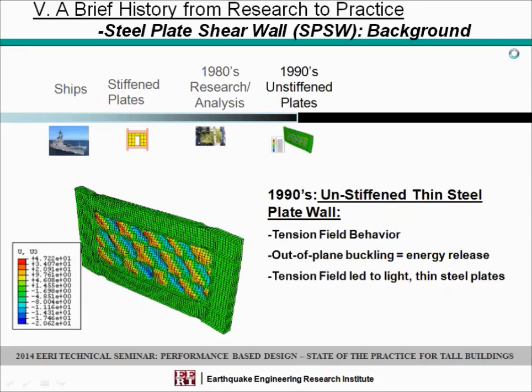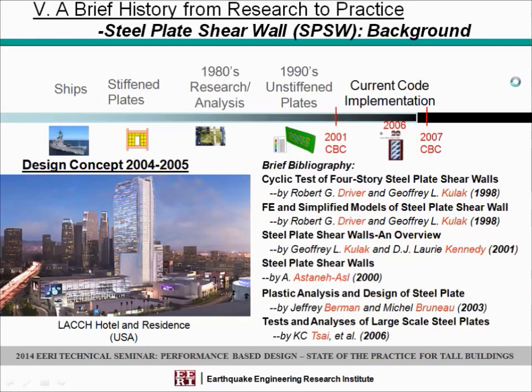That's a follow-up test in the 90s, and that kind of confirmed the tension field behavior and the out-of-plane buckling as an energy release rather than a limit state. Tension field led to the light and thin plate concepts. I skipped considerably because we had to reduce this.